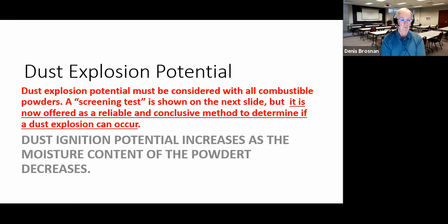Now, of course, lighting one of these kilns is pretty exciting. You have to get the kiln above the auto ignition temperature of the solid fuel in order for it to burn in the kiln. And so there are various techniques to do this with gas burners. I've even known of people loading up kiln cars with wood and running them through the kiln on fire while they start injecting the coal until they get up to the temperature at which the coal will automatically stay ignited. When the kiln's hot, then the product is run through the kiln.